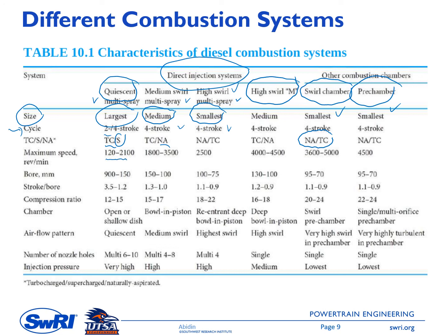You know well already that the large engine is usually operated under low engine speed. If you remember why, it is because we need to maintain the same piston speed. Because a large engine has a longer stroke, we need a smaller engine speed. And for the smaller engine size, because the stroke is shorter, you can operate the engine at high engine speed. And then the next ones are the bore, stroke, and so on.